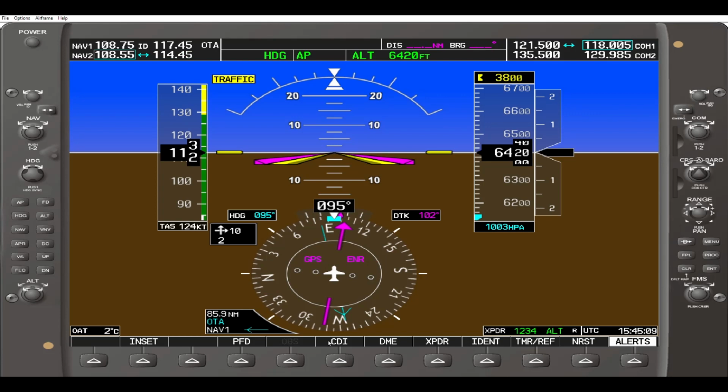There is also a third CDI option, and that is the GPS. So if the source of navigation is GPS, in general in the philosophy of Garmin, it's displayed in this pink color. It's called magenta. So if you see something, for example a track on a map, and it's a magenta line, that means that it's generated to be used by following a GPS signal.